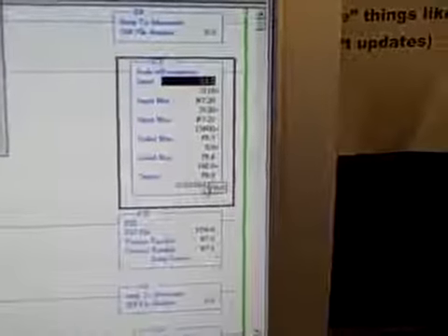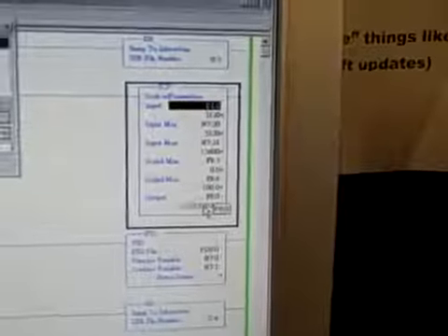So let's suppose we wanted this to express the process variable in terms of percent instead of PSI. I could simply change that to 100, representing 100%. There we go, 100. I hit the enter button, and as soon as I do that, you see that number value updated there, and lo and behold, we're going to be scaled in percent here instead of PSI.